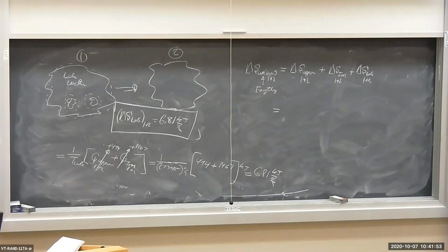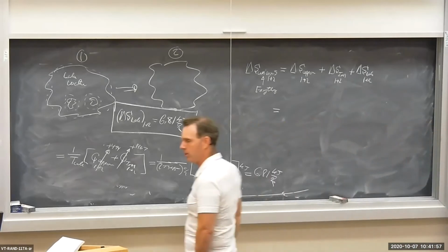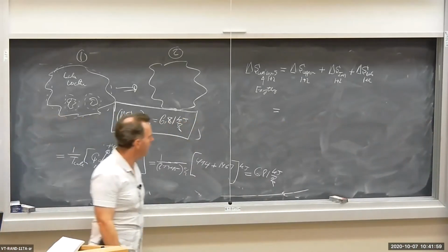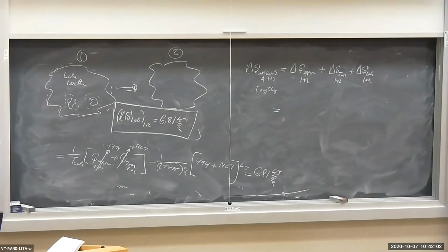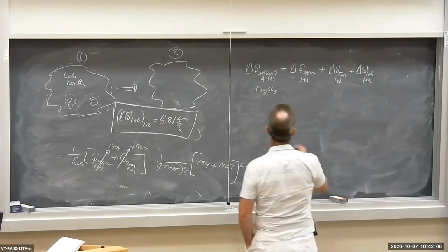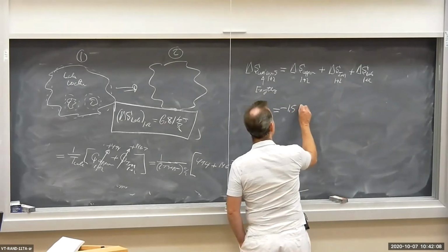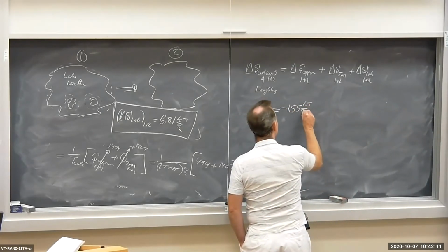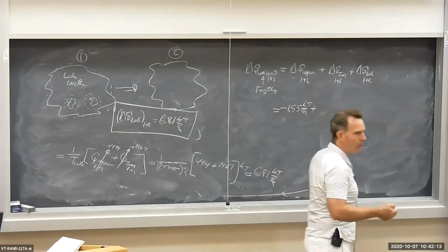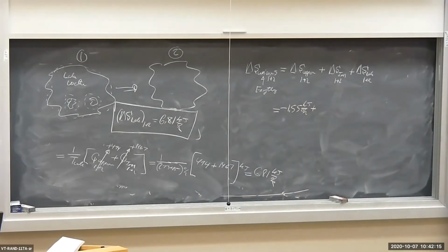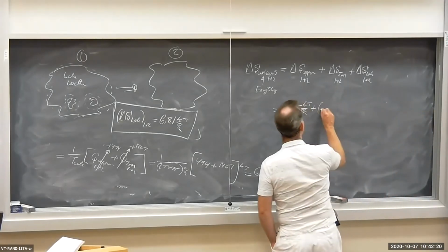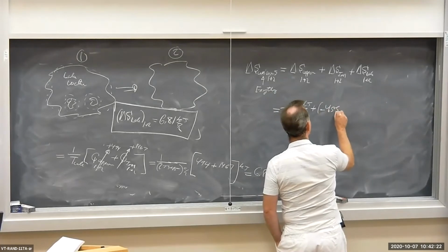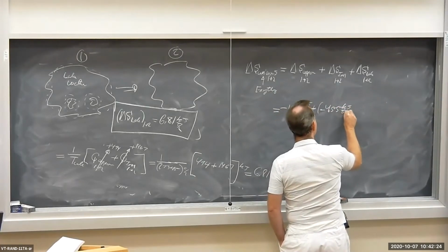So let's calculate the change in entropy of everything. My lake plus my lumps of iron and copper. Let's see here, delta S for the copper, that was negative 1.55 kilojoule per degree Kelvin. Okay, so we lost heat to cool down the copper, so entropy fell. Same thing for the iron. Negative 4.55 kilojoules per degree Kelvin.